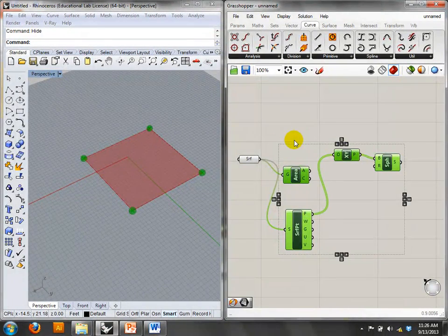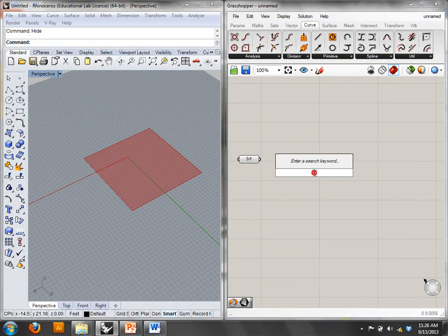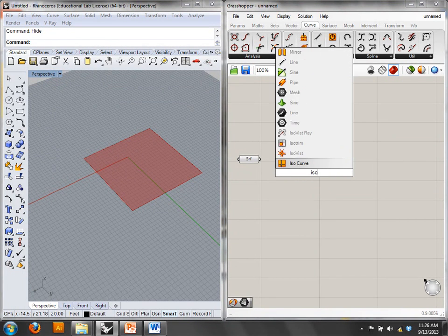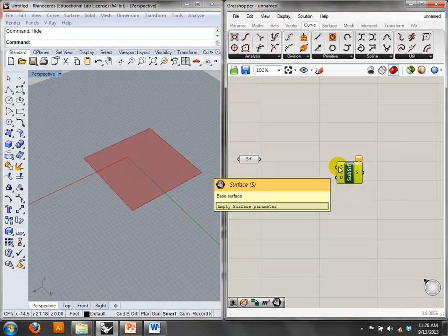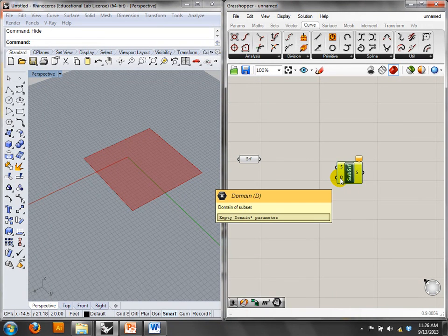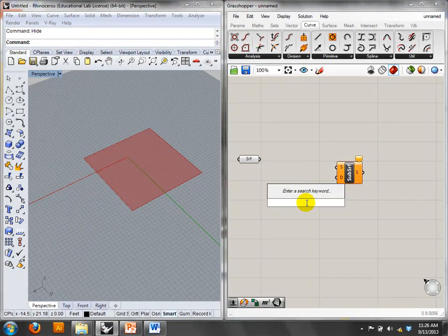When it starts to get interesting is when you can divide a surface up, and this is a pattern that I want you guys to know. We'll use this one all the time. So this is the divide surface pattern. You're going to start with an iso trim. An iso trim wants a surface, and it wants a domain, and the domain is basically instructions for the butcher to chop up this beast into cuts, okay? And you'll see this a lot. I'll show some videos. Eventually I'm going to start glossing over it because it's such a common thing to do.